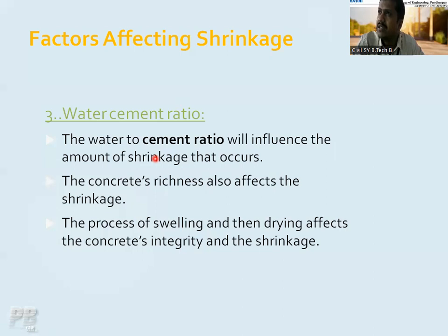Once there is a change in the temperature or due to the action of the weather, some water may get evaporated from that concrete body itself when the temperature rises. Now, if you have used a very low water cement ratio, and the temperature goes on increasing, what will happen? It will start shrinking, and then you are going to see some failures like honeycombing and some cracks being developed. That is why it is important for us to select the exact water to cement ratio in our concrete structure.